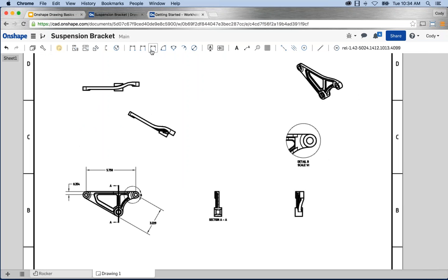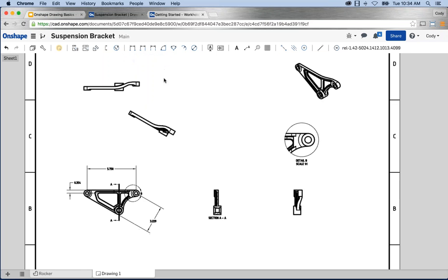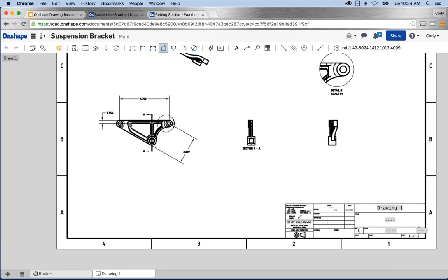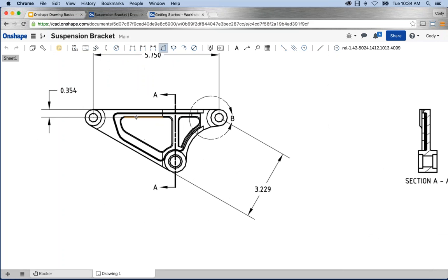So let's move on. Now, I've covered point, line, 2 different dimension types. It really just depends what you're trying to reference. But they're all linear dimensions, distance between 2 things. Then we start getting into other different dimension types. So for example, an angular dimension, line to line angular dimension. The idea behind it is you select a line, and you get an angle value, right? Because these lines are not parallel, of course, you get the angle.